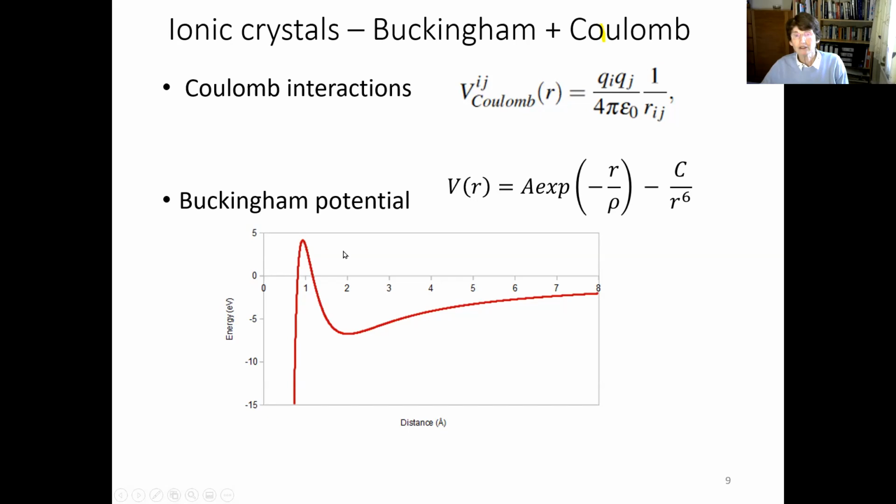It doesn't usually matter, because usually we do our simulations close to equilibrium, close to the bottom of the well. But sometimes if you start a simulation far from equilibrium, the forces can be large enough to actually cross this barrier, and the simulation will fail quite quickly, and you might wonder why. That's something you need to be aware of. And in that case, you need to go back and get rid of all the large forces before you restart your simulation.